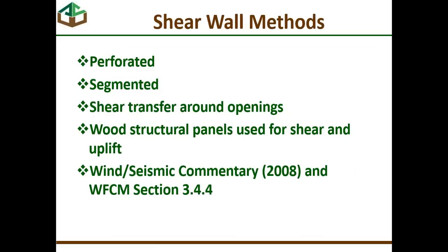There are a couple of shear wall methods: perforated, segmented, and then one we're not going to talk about at all, really, which is trying to develop shear transfer around the openings. Almost no practitioner uses that method that I know of. It's too complicated and takes too much time. But there are tables to use for perforated and segmented shear walls.